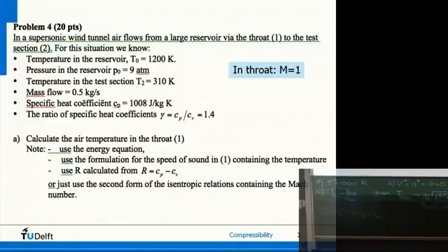Both is actually fine. We need the temperature and we need the speed. We have the temperature and the speed in the throat. Perfectly fine, it works. Reservoir, we have the speed, almost 0, so we can assume 0, and the temperature, it will work as well. Only the reservoir is a bit less work, because we don't have to compute half V squared, but both is perfectly fine. You can do this, as long as a streamline goes through it, because we integrated it along a streamline, and streamlines of course go from the reservoir through the throat to the test section.